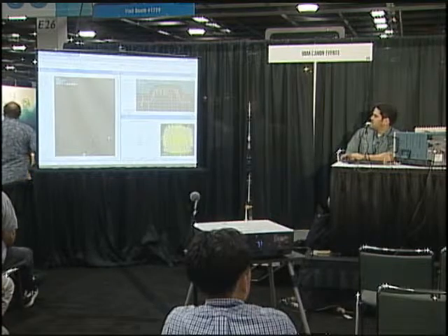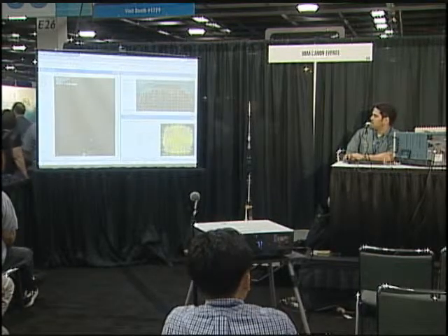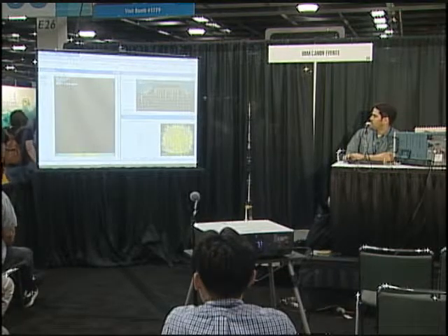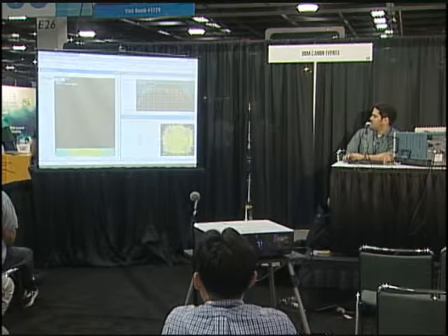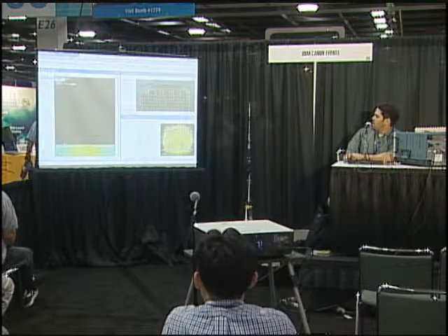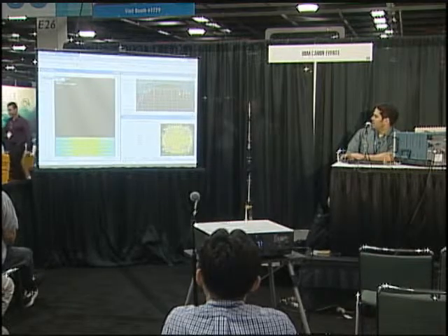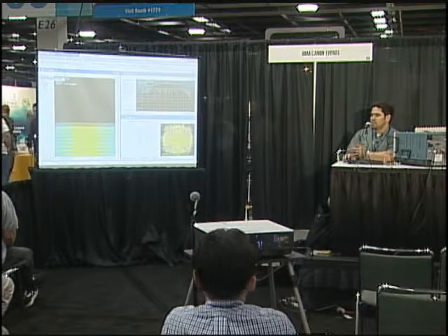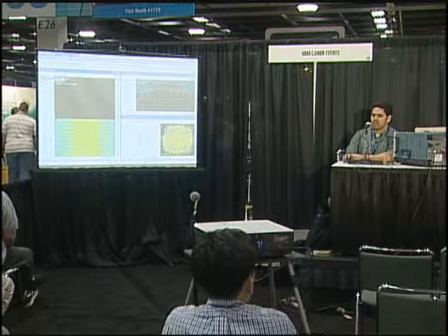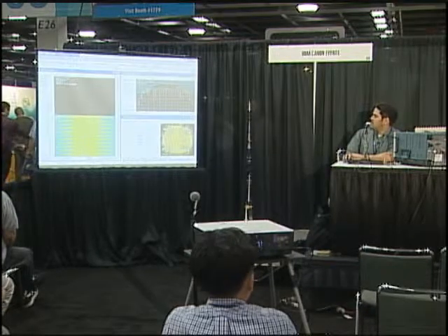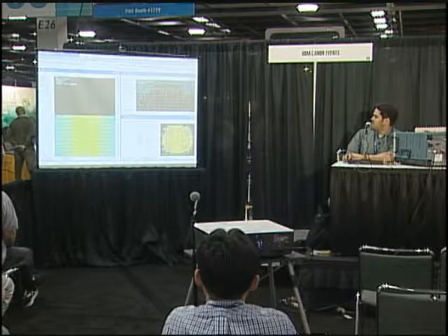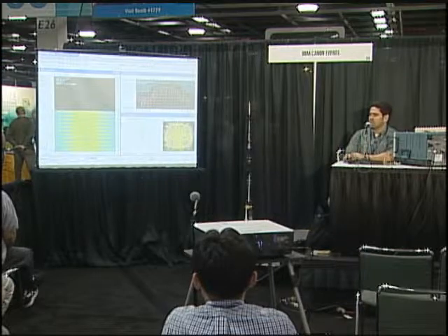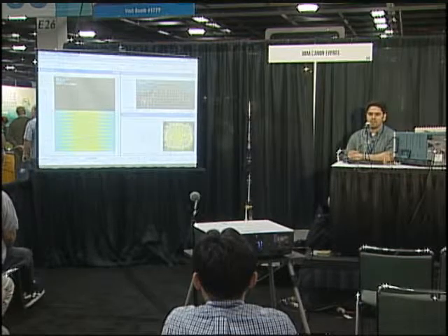And so what we get here is the same scenario as before, but now we're triggering with a frequency mask. Let this run for a little bit. And so once again, we are triggering this time with a frequency mask. And you can see that the Constellation looks really bad and EVM is really bad because we are doing the demodulation right at the time those shoulders are coming up. We can pause this, and you can see this is good signal, bad signal, and so on. And every one of these little tick areas here is an acquisition. And between them, there could be seconds, minutes, hours.